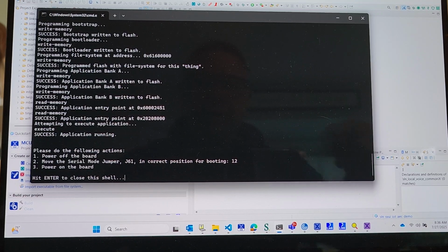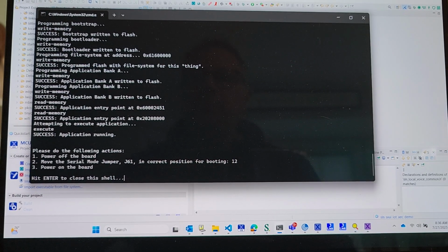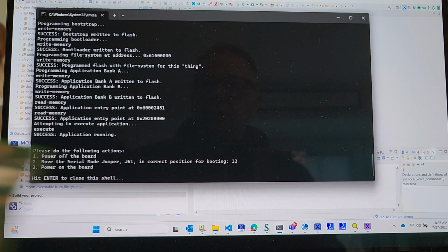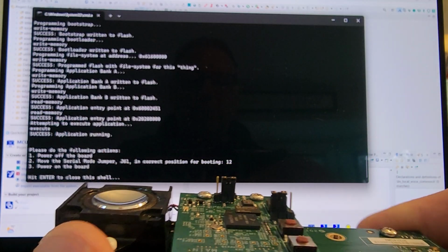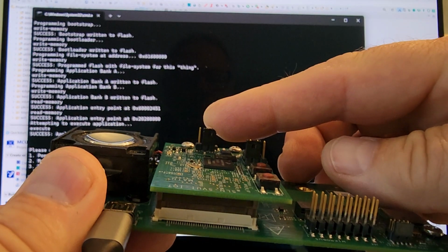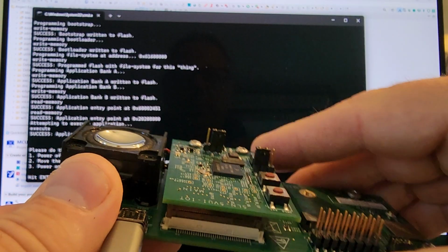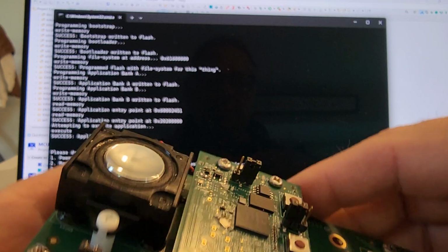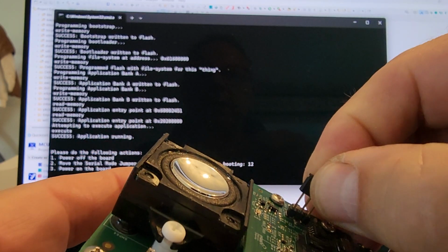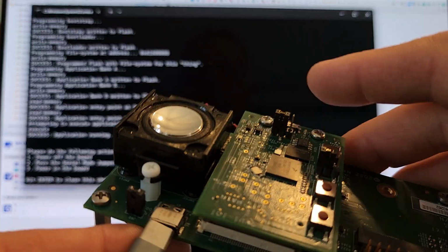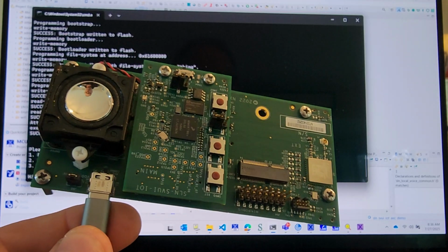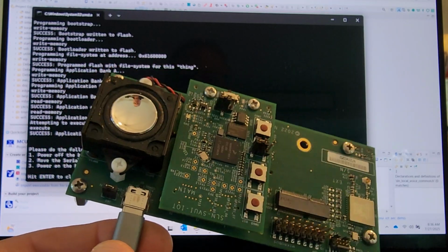Okay, I ran through this flash programming bat file again because HVAC demo. This is what you should be seeing over here. So once again, when I was programming it, I had to move the jumper wires. So we have to shut off the power, move the jumper wire back to the other pins 1 and 2, turn it back on. HVAC demo. Now we have the demos running.